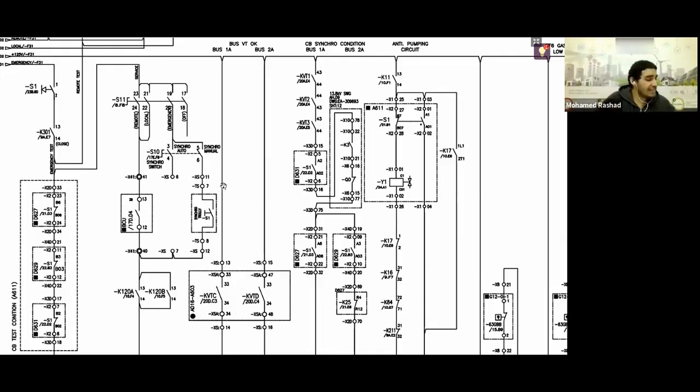I have verified several conditions. All right, my condition is that the VT isolator is closed, the VT MCB in the box above is closed, and the VT MCB in the LCC below is closed. So these are the three conditions above.